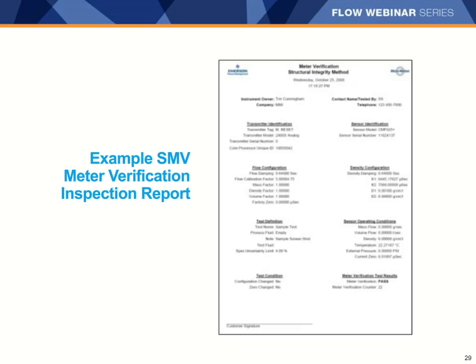The SMV diagnostic tool provides a comprehensive print-ready report for your quality records that includes not just the results of the important flow tube stiffness test, but also includes other pertinent data, including a record of the integrity of the meter parameter configurations and the process conditions at the time of the test, as well as the health of the electronics of the meter and every other secondary diagnostic check that is performed simultaneously.